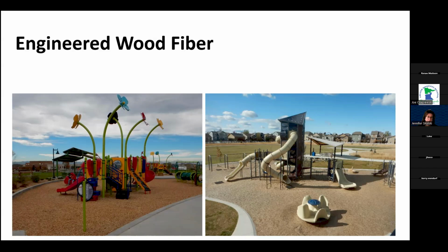It goes through multiple processes between a chipper and a compaction or a pressing process to flatten out the wood chip and to make it so that it would knit together. And so that's its primary difference. And then the ASTM standard actually has requirements for the sieve size and the percentage of the sample that has to meet the requirements for certain types of sizes of the sieve.